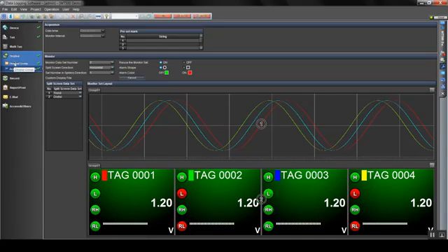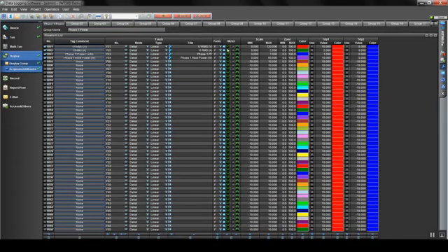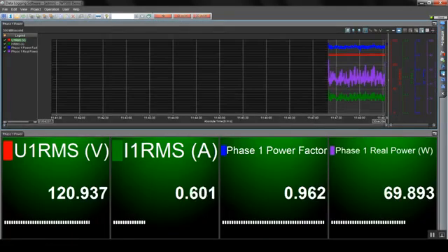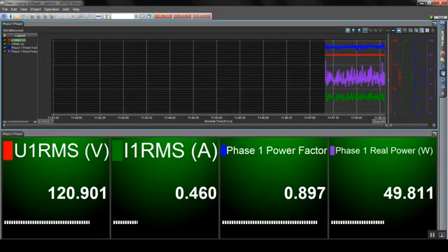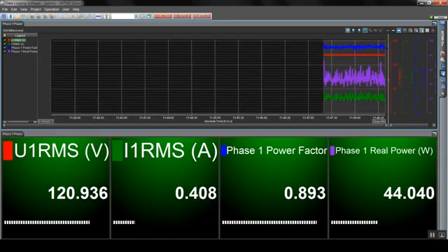I want to be able to show that signal on the lower end. I'm going to go back to Display Groups to change that value from 120 to 150. And I go back, and you can clearly see the signal is now within the range, and it's easier to see. In conclusion, I want to offer a quick review of what we discussed.